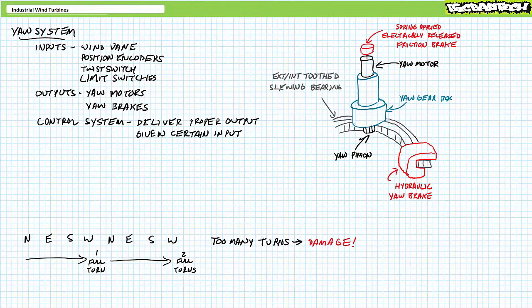For this reason, in addition to keeping track of present angular position, the controller also keeps track of how many full revolutions in one direction have been accomplished. At a certain point, maybe 3 or 4 full twists in one direction, the controller is like, enough. Let's unwind, and momentarily halts production to unwind an equal number of full turns backward in the opposite direction, resetting the cable bundle to a slack position. Additionally, the turbine controller takes advantage of extended periods of low or no wind conditions when production ceases to take the time to unwind to a slack condition.